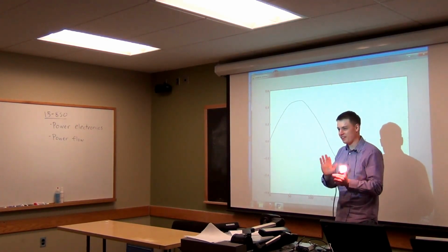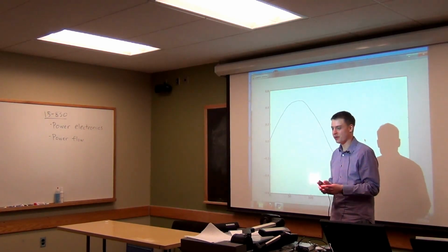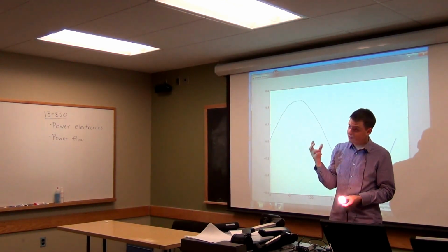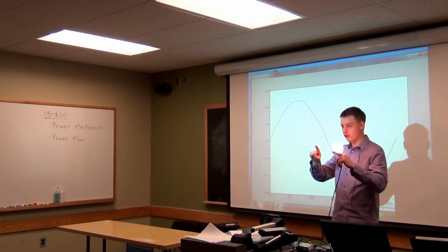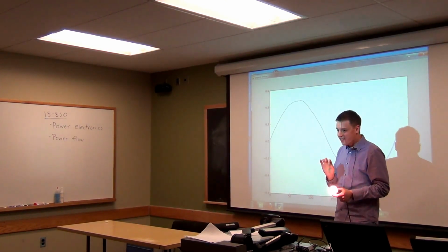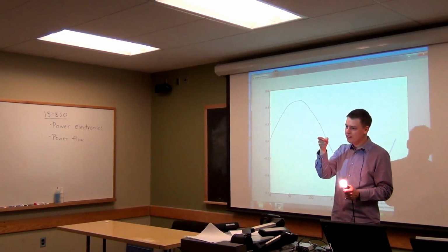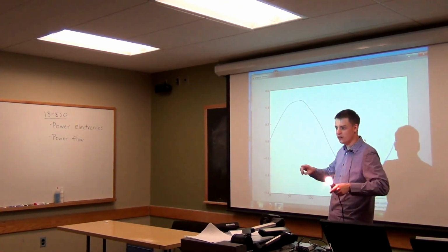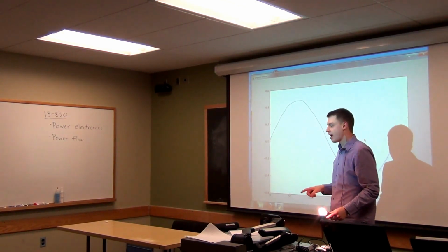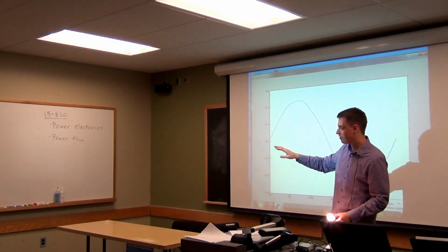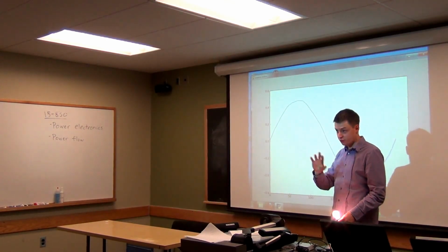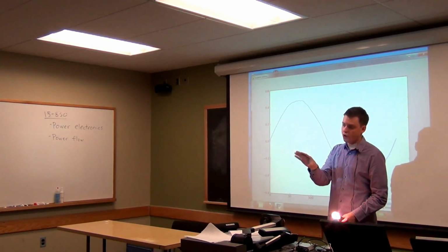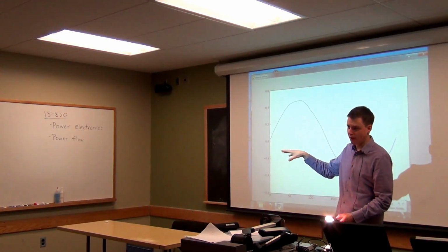When it comes into the home, again, if you haven't heard about this or don't know the story here, don't worry about it. But often in the US, you'll have two phases of power in a home. And so you'll have two phases that are 180 degrees out of phase. And what's happening here is that this is still just tapping one of the three phases of power on the transmission lines. But then when it comes to your house, you tap it in two different directions, and you get two phases of power that are 180 degrees out of phase. And so that's how you get some amount of power that is 120 and some that is 240. The 240 things will use both those two phases, and the 120 will just use one of the phases. But for the majority of the time, you are only seeing one phase of power or one of those three phases of power in what you see.